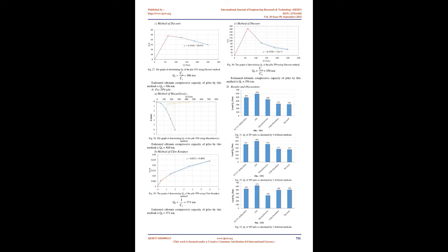Case 2, based on the formula of the Architectural Institute of Japan, AIJ, 1988, also shown in the appendix of Vietnamese Standard TCVN 10304:2014, Section G 3.2. Compressive loading and unloading are shown in Figures 11, 12, 13, and 14 respectively. The value of pile head displacement corresponding to each level of compressive load with the maximum at each stage of the piles is summarized in Table 4.